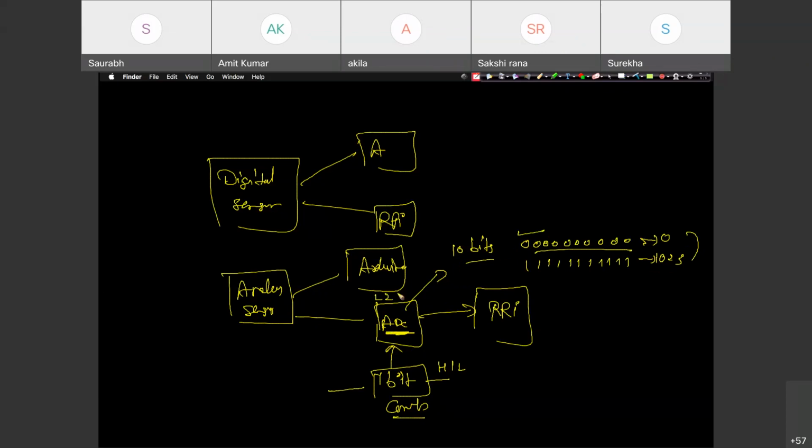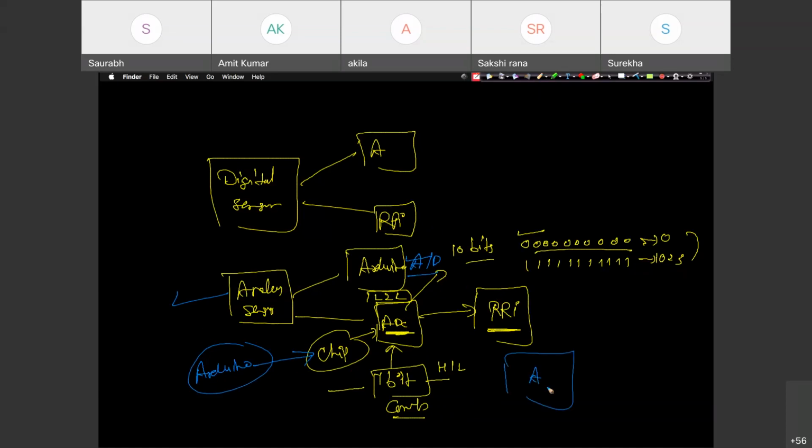You can have ladder to ladder, R to R, many different models for converting your analog data into digital, and then you can start working with Raspberry Pi. So you can have your chip here, and again another chip, another hardware, another interfacing would be required in between. Or else you can replace this entire thing with Arduino also, because Arduino has analog and digital interfacing both, right? So what I'll suggest, if you have an analog sensor to work upon, better use the analog sensor with Arduino, and then Raspberry Pi.